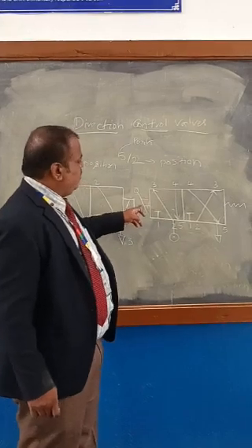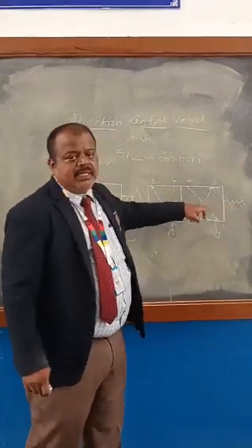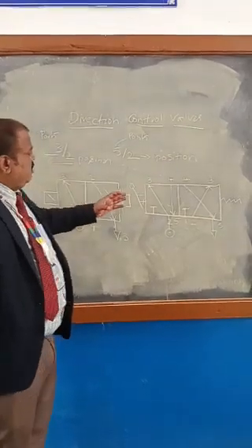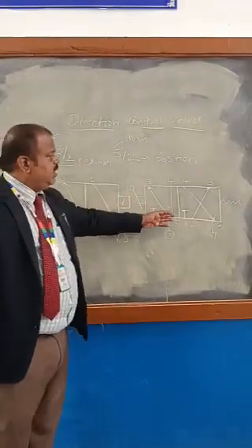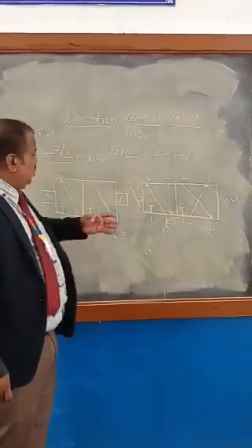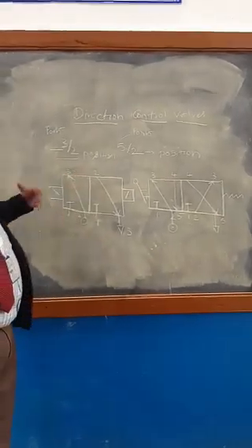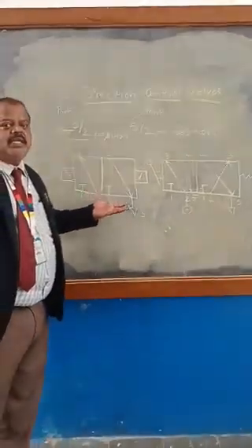Okay, on one side it is hand lever, and the retraction will be by the spring. So this is about the 2 types of direction control valves: one is 3x2 and the second one is 5x2. Now we will see how this 3x2 direction control valve is applied in a pneumatic system.